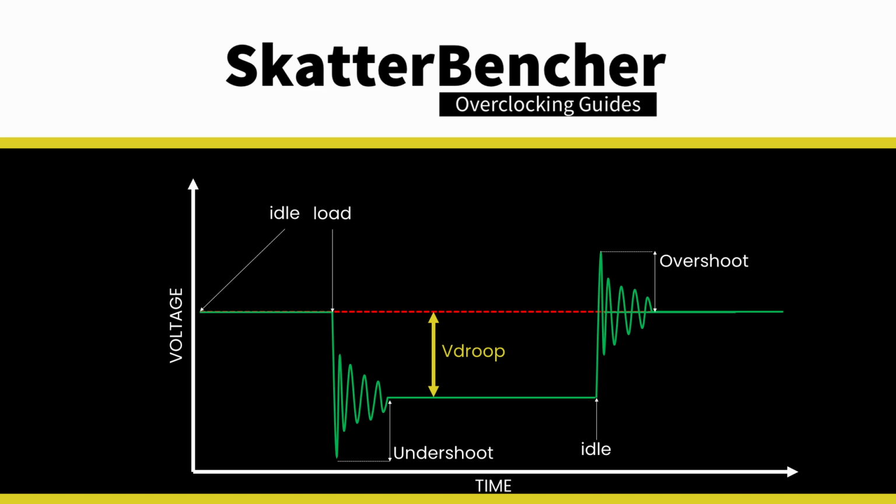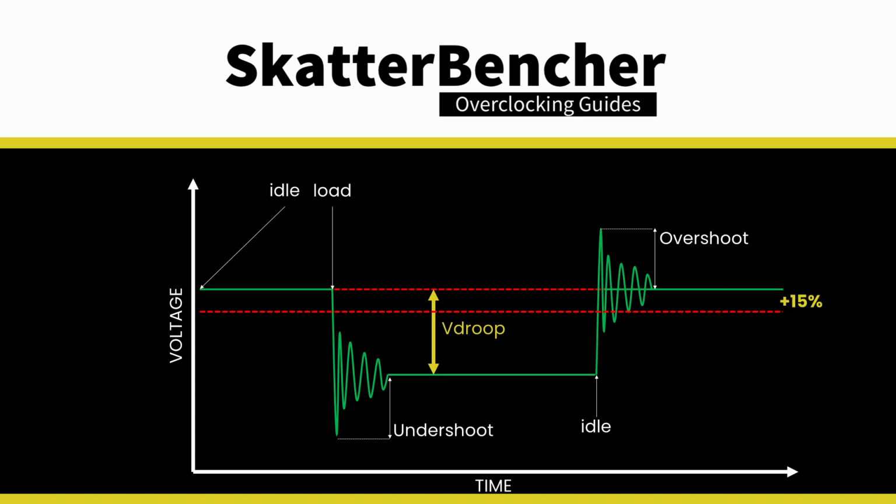The problem with voltage droops is very well known to overclockers. A voltage droop can cause the operating voltage to fall too low, causing system instability. In the past, chip designers would address this issue by supplying 10 to 15% excess voltage to ensure the chip always has sufficient voltage even after a significant voltage droop.